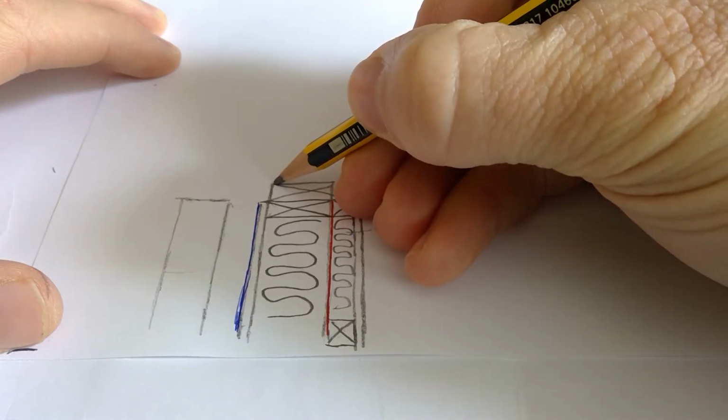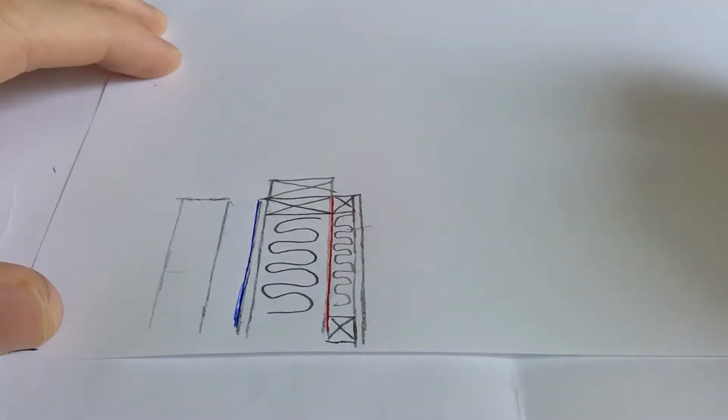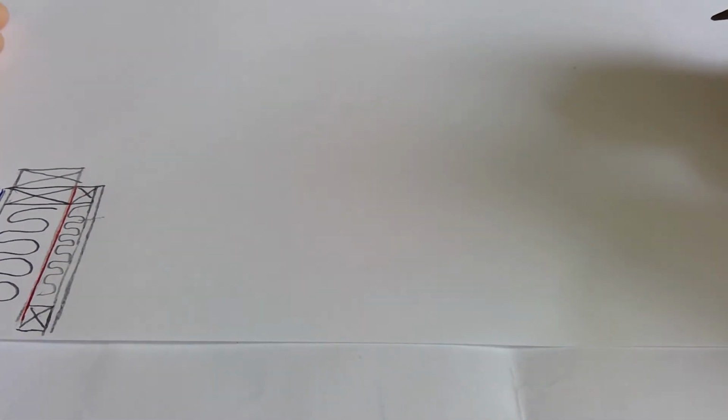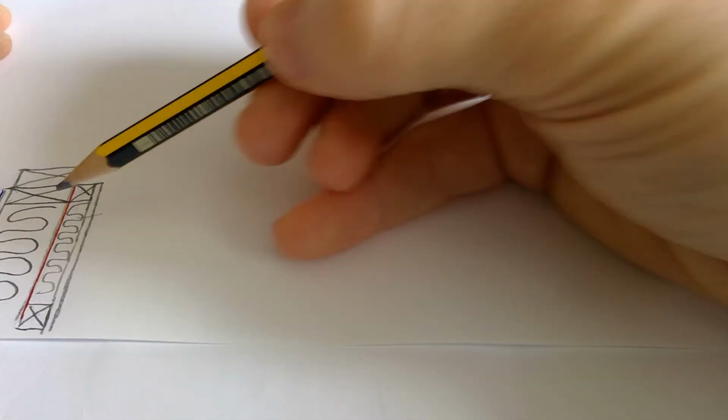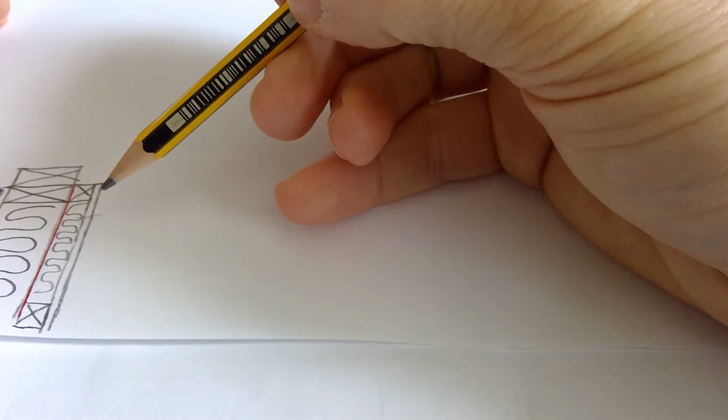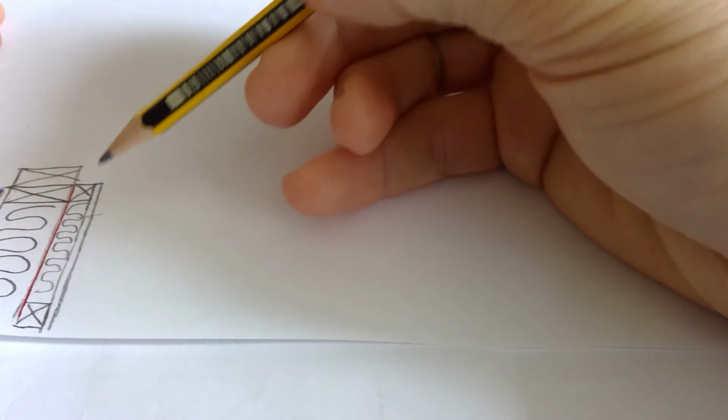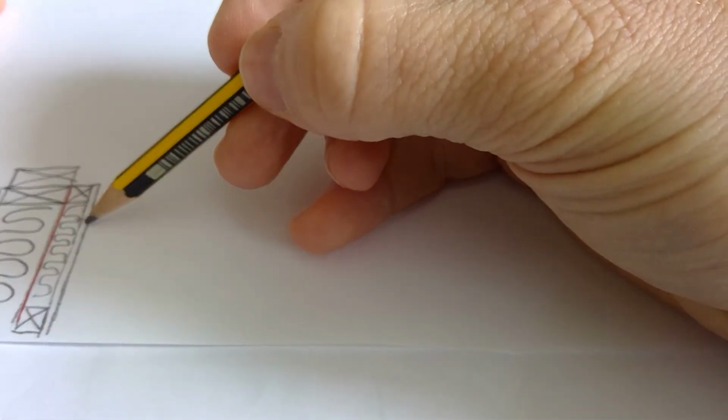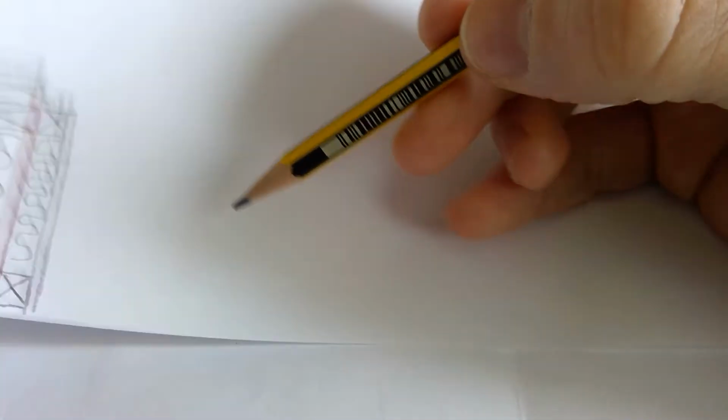So we have to draw half of the roof. So we want to know how far across here we have to go as well. The question said that the whole roof is 600 millimeters. The internal span, that's the inside of the wall to the inside of the other wall. So to get halfway, that will obviously be 3 meters. When we scale it down, it's 300 millimeters. So you'll measure across here your 300 millimeters and just draw a light line up there. So you know that's how far across you have to go for your drawing.